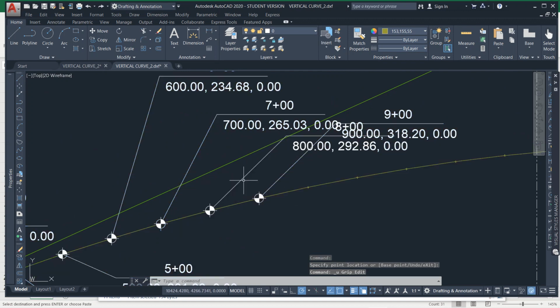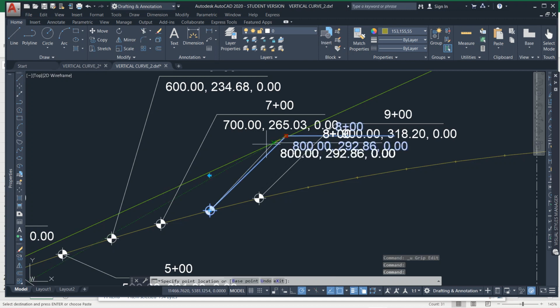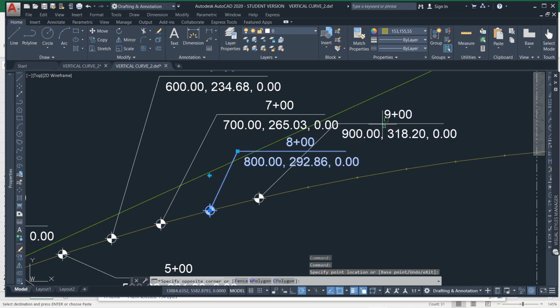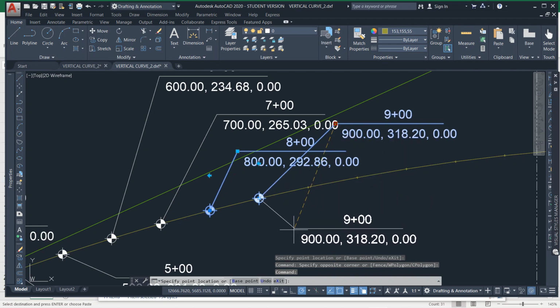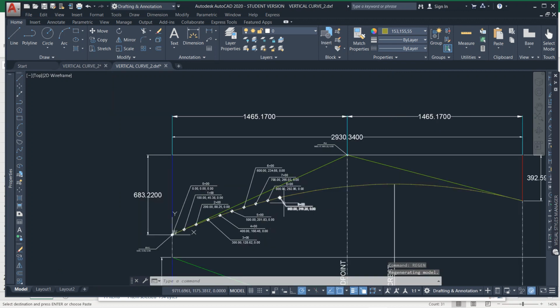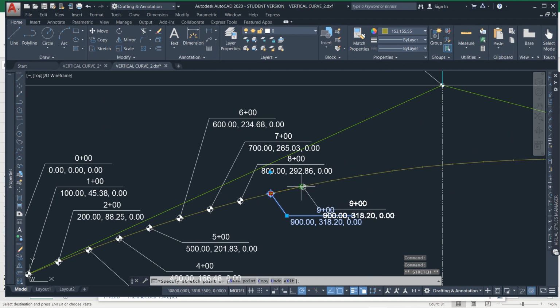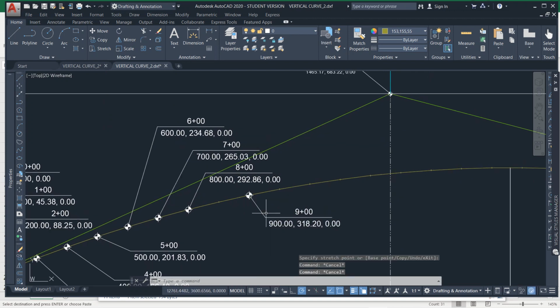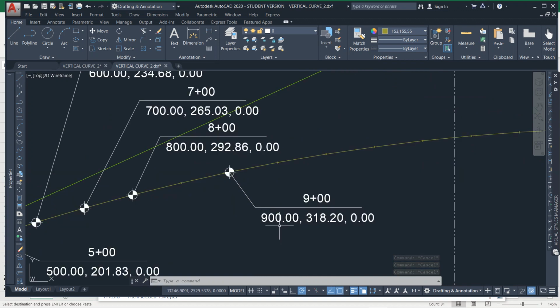So that's how you get it. And then you've got to remember those are all updated as you put them in, but then regen. Let's say this moves to there and you realize there are some errors and you need to start changing, so you need to hit regen. See, look, it's at 900, comma, regen, and it's at 1,000. It doesn't update without you hitting regen.